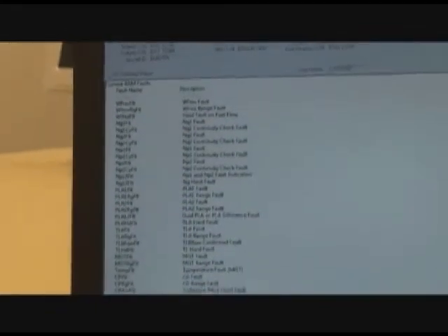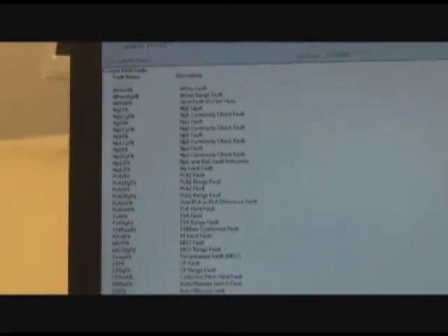That will lead us to the ECU summary page, and there will be numerous faults and current faults for this particular case, when the ECU is not connected on the aircraft, and these are all faults because there are no harnesses connected to them. But the next step on the bulletin is to go to Engine History and hit View.